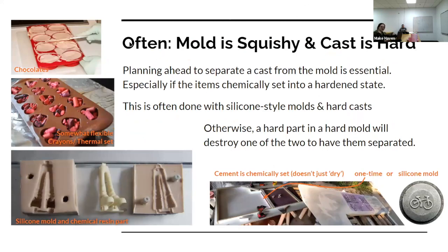So most of the time, the mold material is the pliable thing. It'll be squishy, or it could be disassembled, or it comes apart. The majority of the time, that's going to be what happens. And the more crazy your shape is, the softer the material needs to be to make it work. If not, you run into issues. It can damage your castings as they're coming out, or damage the mold itself. That will also cause wear and tear on the mold.